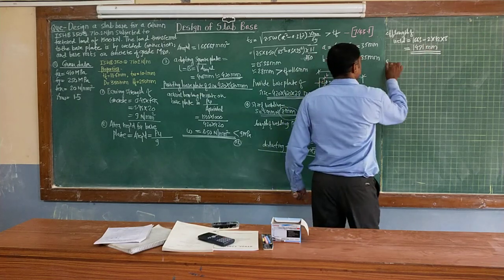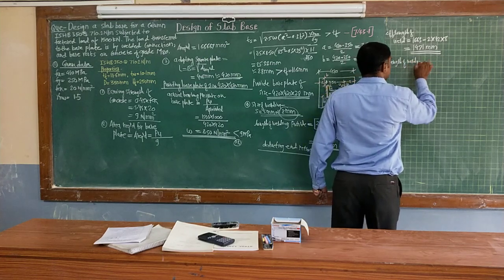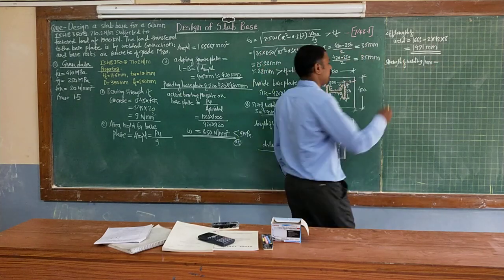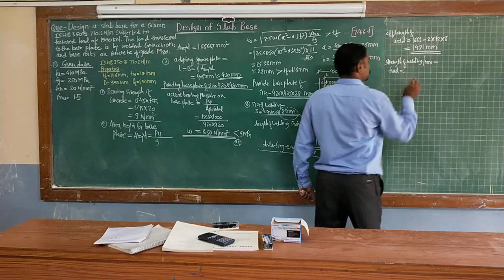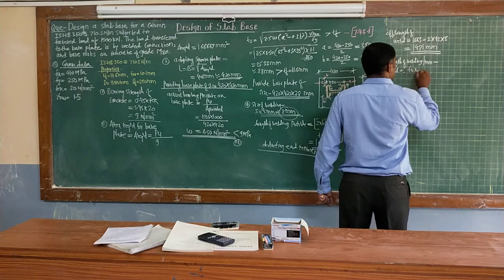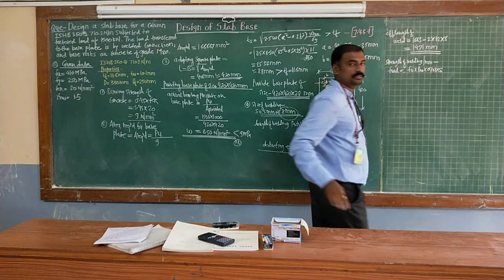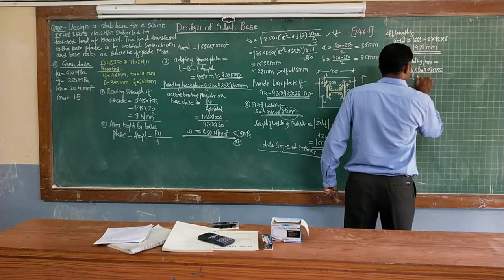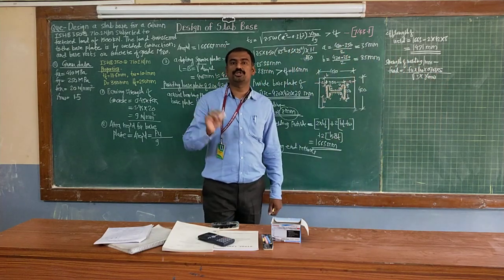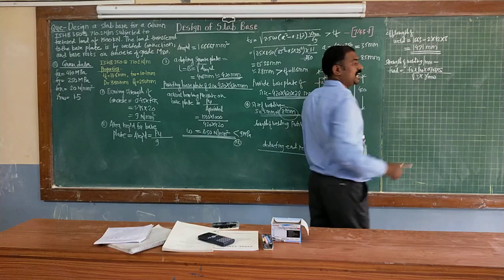Correct? Now strength of welding per mm distance. So we have the formula FWD, that is ultimate design strength of welding, is equal to FU multiplied by length of welding into 0.707 into size of welding divided by root 3 into gamma MW. So already we have discussed partial safety factor gamma MW should be 1.5 because this we are doing directly in the field.